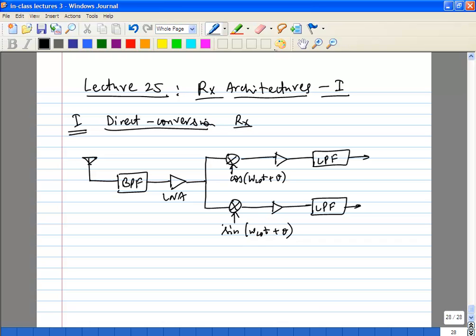Because the input will be a single frequency signal, right? No, it's not a single frequency, it's a band of frequency, a band limited signal which is modulated by a single frequency. So the output frequency you can expect to shift to some other frequency? No. Both the Xi of t and Xq of t are at the same frequency. They just have different modulation. Well, they have independent modulation. Yes, that's exactly right. I was confused about how you generate the independent modulation. Okay, I can take a look at it and get back to you. I am not sure how exactly they do it in the baseband.